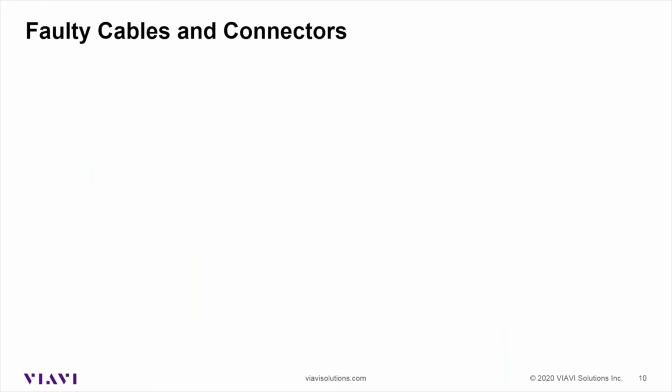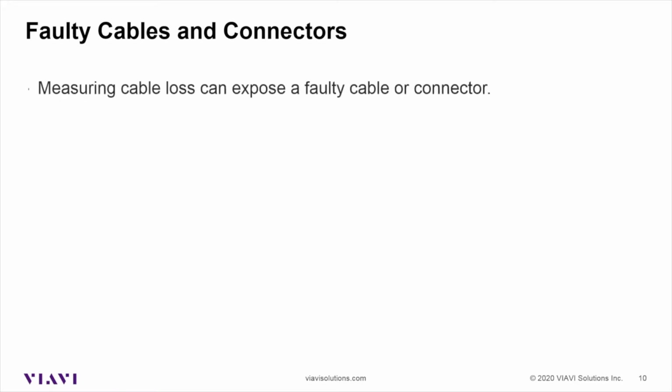One of the things we run into from time to time is errors in measurements caused by faulty cables and connectors. And sometimes that means that the cable itself has been damaged. So maybe it was slammed in a drawer somewhere and it's pinched. And typically that type of thing, it'll cause a high VSWR, and we get a change in the frequency response. Sometimes it's enough to actually cause the radio to fault for high reflected power. So there's lots of things that can happen, but it usually results in some sort of frequency response issue, okay?